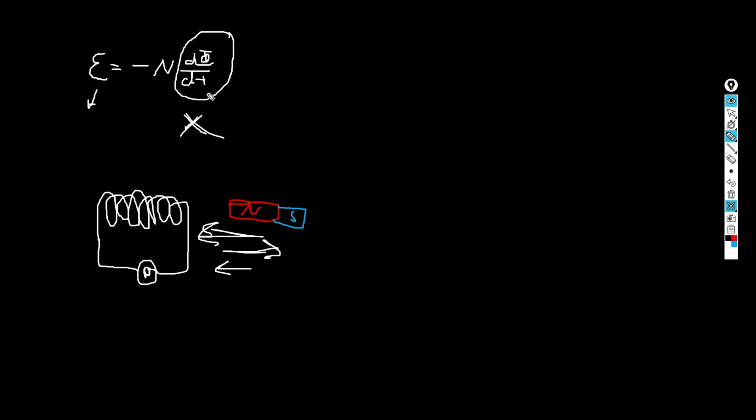How could you increase the voltage? By using a stronger magnet, increasing delta phi, the change in magnetic flux, or moving it faster, decreasing the time, or using more turns in the coil, right? But guys, this is very important. They might ask about this. If they're both moving together in the same direction, so they're not changing with respect to each other, there is no induced EMF.